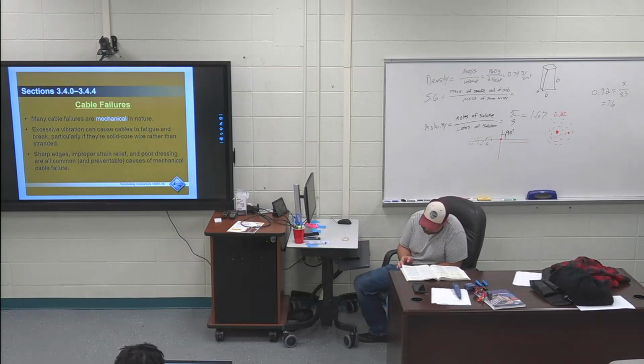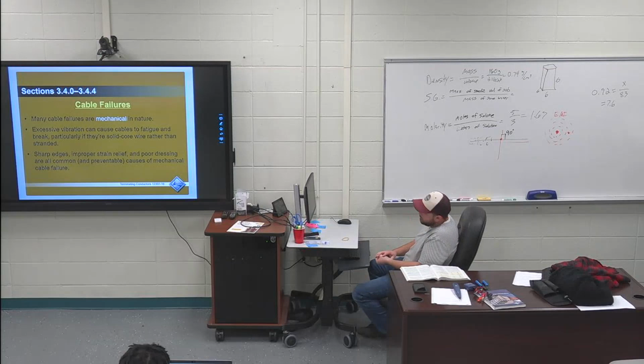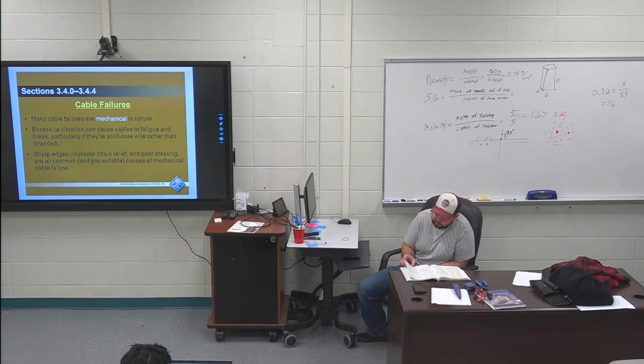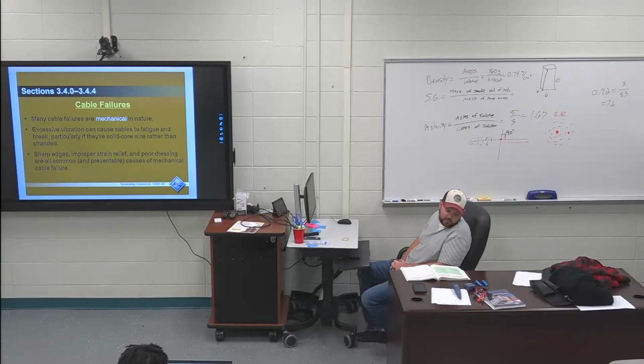The next paragraph, I've got the second, third, and fourth sentence highlighted. So starting at the bottom right of page 49, cables used in air spaces, such as those above suspended ceilings and in air plenums, must be rated for safe behavior during a fire. Many ordinary cables will burn or melt and release toxic fumes that can spread through the airspace into other areas. For this reason, special plenum-rated cables are available for these installations.